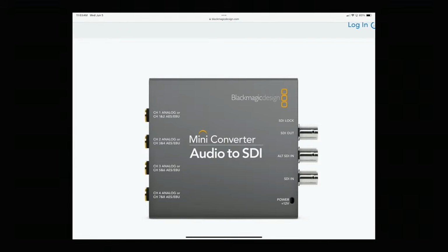I will tell you, I've used this technique, and I've actually had problems where the channels swapped when, in rebooting the system, HDMI reconnected or SDI reconnected. I was going HDMI to SDI into the SDI embedder box, back to HDMI into an ATEM Mini Extreme. Depending on the day, left would come up as left, or another day left would come up as right, and then you'd repower the embedder and you'd get things in the correct order. So I will give you that to watch out for. I think that's a sync connection in the digital system.